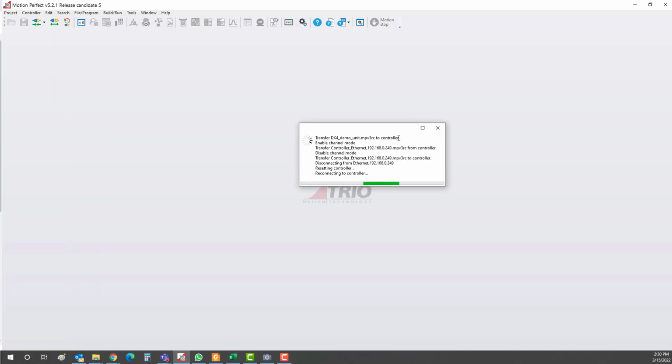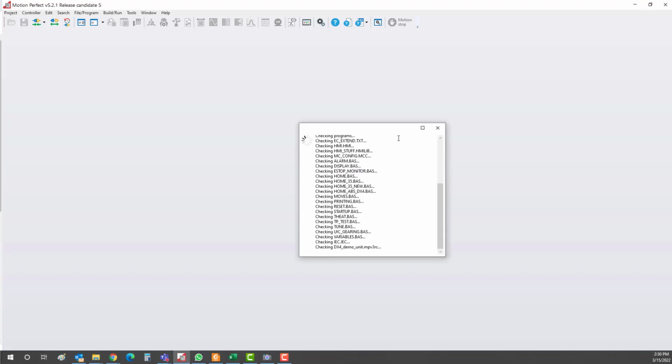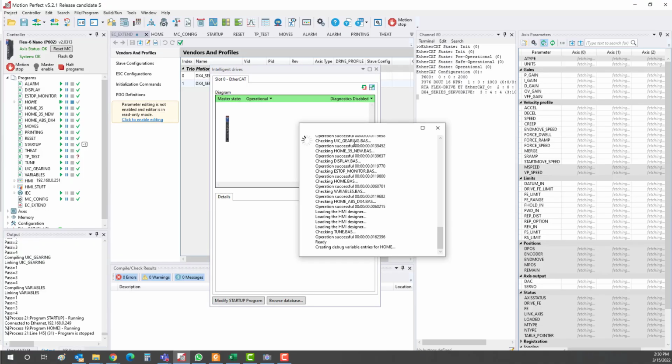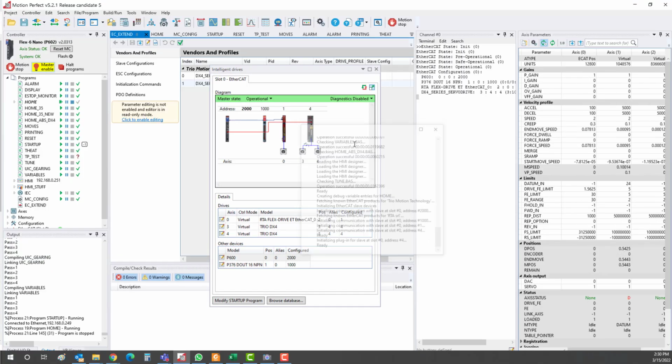Yeah, this is a new option for us. So there is still some ongoing process to make it more functional and much easier to pick. But this is a very useful option for you. You can imagine in some project that you have some external encoders and you have the DX4. Instead of ordering a module to read the encoder, you can use the DX4 built-in function to read the encoder, which can save you a couple of $100 in the project.